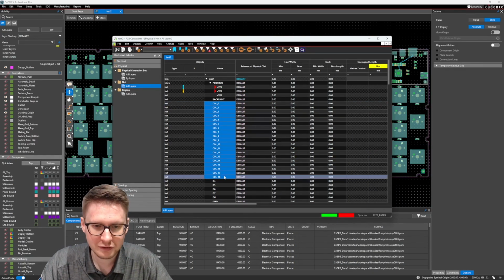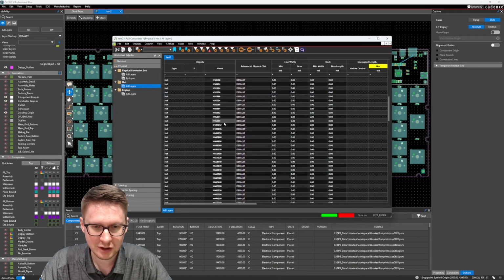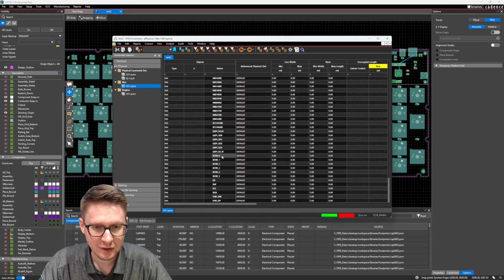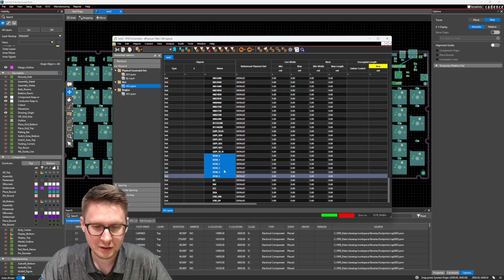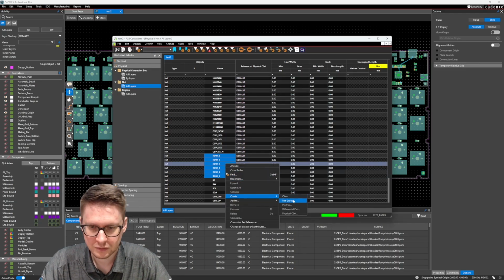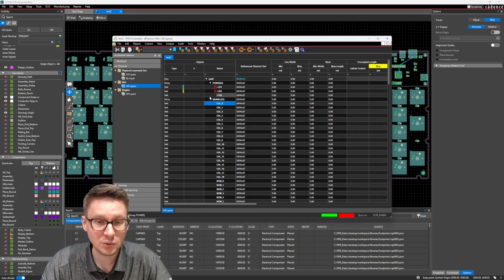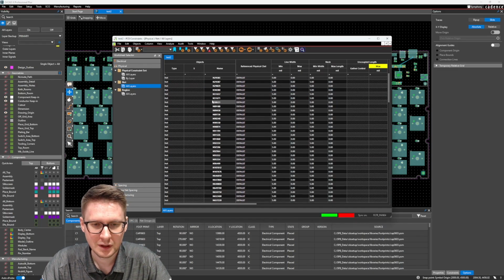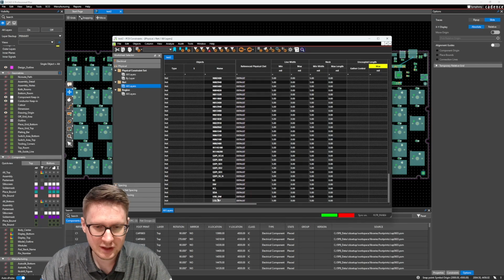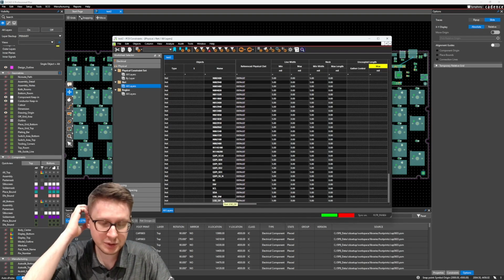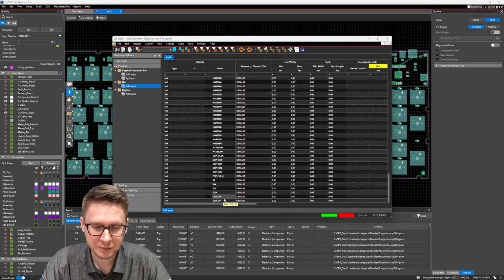And for example, all of our column and all of our row nets are what we would call signal nets. So we'll add those to a group called signal. If we keep scrolling through here, we can see that we have, for example, USB D, P, and DM. These are like digital signals, right? We have our serial clock and serial data for our I2C, read, write, some QSPI signals.